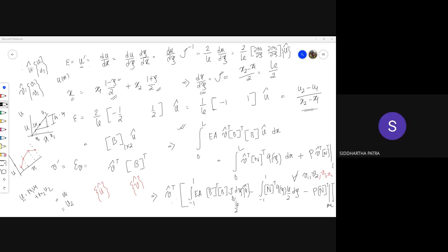Okay. So you see, the weak form involves the symmetric bilinear form, half A U V, which basically means we treat V the same way we did U. Understood? Okay. But therefore, we would encounter terms which look similar to the terms corresponding to U. If you have U prime, then you also have V prime. And you don't have to call it anything. I'm just calling it variation of strain, and representing it as epsilon of V. But it is nothing. It's just a mathematical term because that's how the weak form turns out to be.